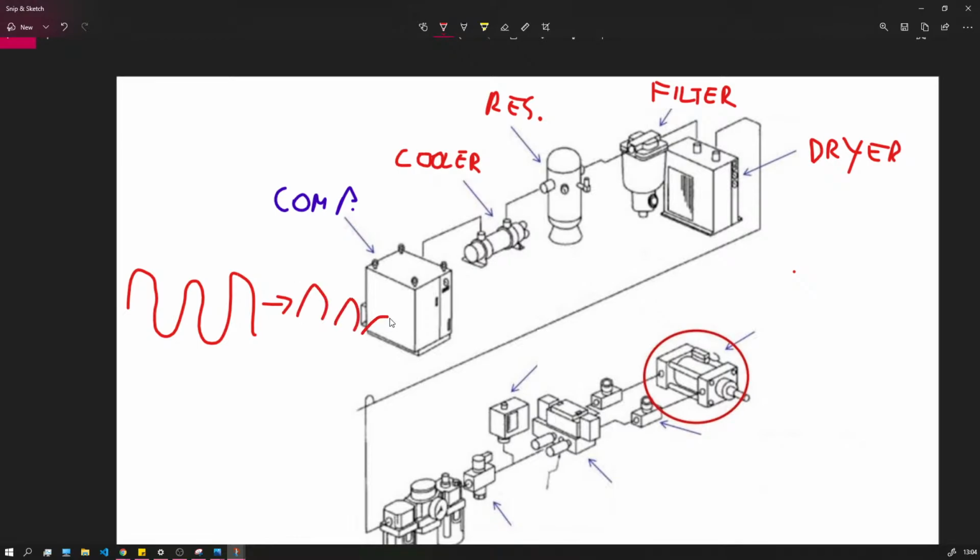We are getting some impulses of produced air, and a diode acts like a rectifier in electrical systems. And to get a good quality DC voltage out of the rectifier, the reservoirs are like capacitors in electrical systems. They're smoothing out and filtering out the changes in pressure and flow rate.